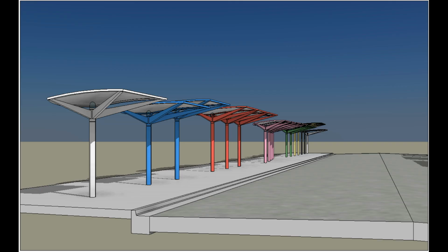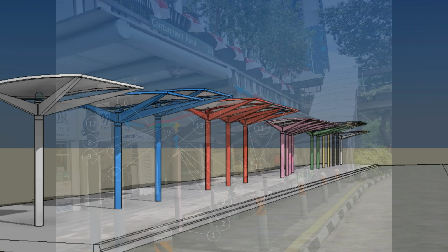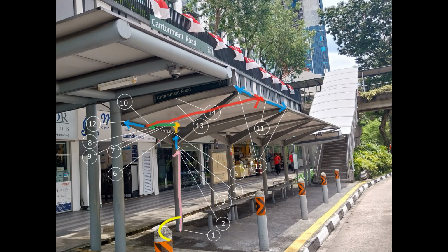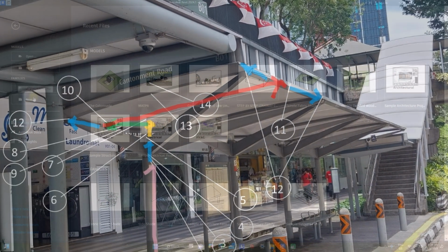Going to start with step-by-step creating the model. This family requires placing one single adaptive point, which initiates the modular skeleton. Referencing this adaptive point number 1, create more reference points number 2, number 3, number 4, number 5, etc., by appropriate working planes and referencing each other, indicated in this image with step-by-step modeling numbering sequences, to form the modular skeleton.